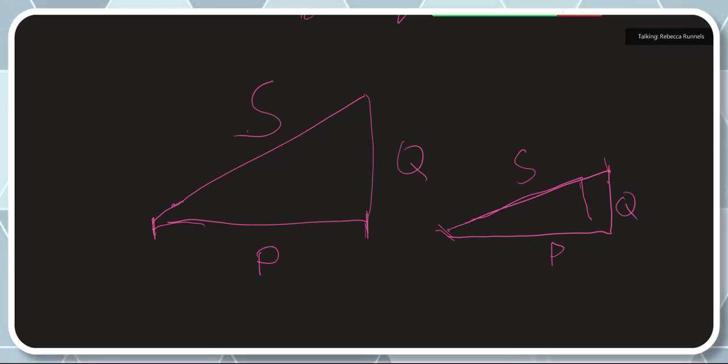The way you would do that would be, because in most real situations, it's not that you have a capacitive load, you end up having an inductive load. That's just what happens with real motors and things like that. So you have an inductive load, and so your reactive power is a positive Q. To bring it down, you would add a capacitor, because that brings in the negative power. When you bring in that capacitor, that shrinks the Q, it shrinks your reactive power, but it keeps the real power the same.